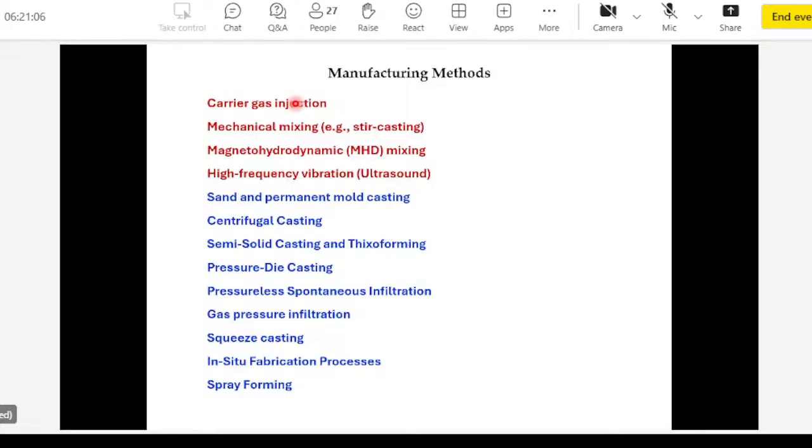The thing is that most ceramic powders behave like plastic beads in water. If you add plastic beads in water, they all try to cluster together. The same thing happens with graphite powder or other ceramics in metal. So you have to stir, but stirring alone is not enough. You have to either supply a coating to the powders, or add magnesium or other reactive elements to uniformly disperse the ceramic powders in the metal.